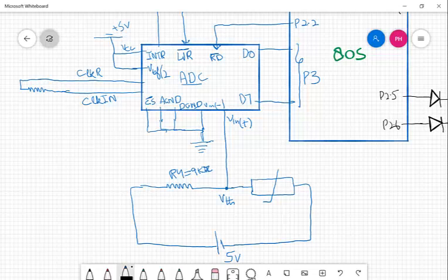A resistor, I will be calling it R5, and it will be equal to 10 kilo ohms. And then we will have a capacitor at the junction of the resistor and clock in of approximately 150 picofarads. That will be grounded also.